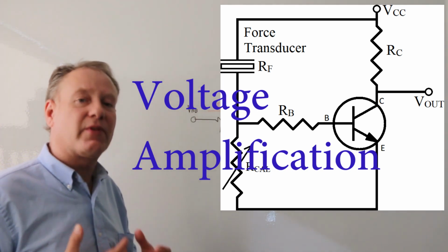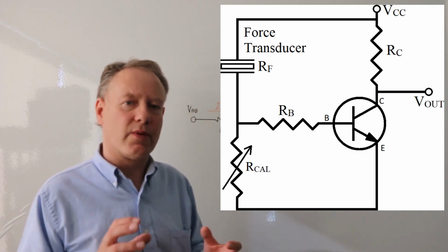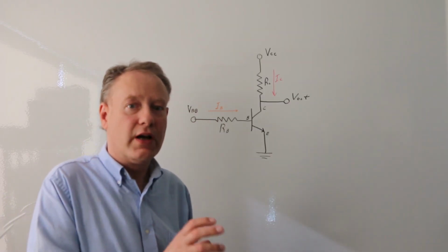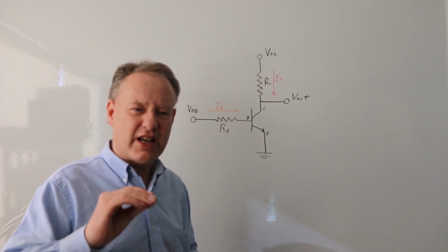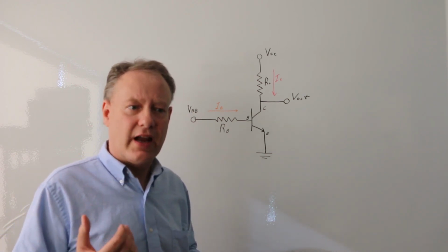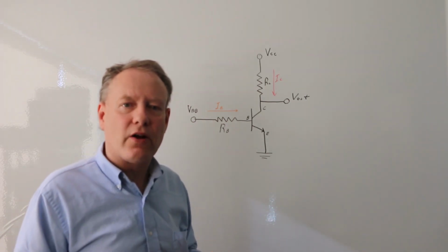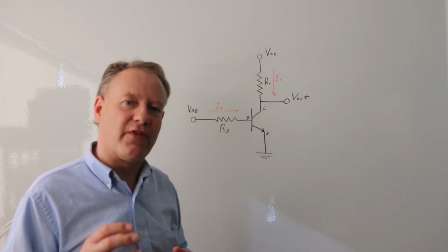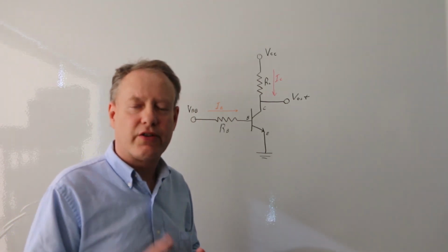In this case, we're not amplifying current, we're amplifying voltage, and we're really taking that voltage and putting it into some other kind of controller that's actually going to make some decisions on that. But the force transducer itself is actually just a variable resistor. And how do we turn that into voltage to go out into a controller? Or how do we actually take variable resistance and amplify that and turn that into controlling the speed of the motor, the current that goes through a motor?